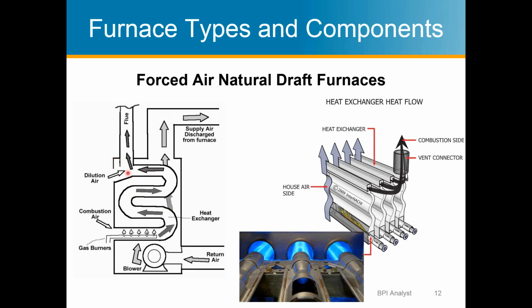The principle that hot air rises, you're negatively impacting that by taking more heat out of this air, so it won't exhaust as well. So that's why usually you see a natural draft furnace topping out at around 78% efficient. They just haven't figured out how to make a natural draft work better than that, because you need that other 22% of heat in the exhaust gases to help it leave the house.